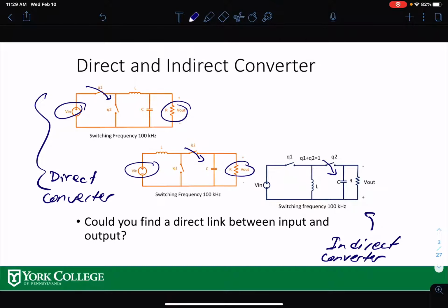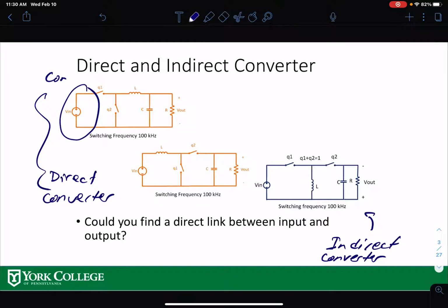All right. So that's that. Then let's talk about something else that's very important for us to know. For this buck converter, this input side has a constant voltage because you're connected to the voltage source right there. And look at what's happening at the output. This is the inductor here. This inductor will keep the current constant. So that means at the output, you have a constant current.